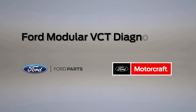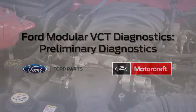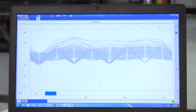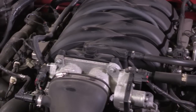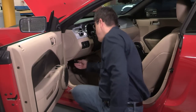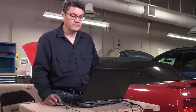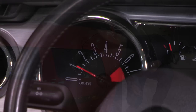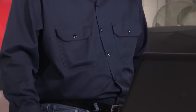Modular variable cam timing, or VCT issues, can be hard to diagnose. Their symptoms often look like something else. Before you start performing a repair on what might be a VCT issue, you need to perform some preliminary diagnostics. In fact, these are good steps to take whenever you have concerns involving misfire, idle quality, or engine noise. First, check for diagnostic trouble codes, or DTCs, in the Powertrain Control Module, or PCM.